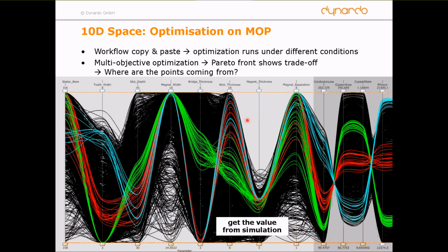The other extreme case is you go through one simulation, you change something, you look at the field lines, you look at the torque, you look at the details, you look at the mesh, you look at everything you can visualize in the simulation, and you can find out, wow, the torque ripples are really coming from here. Look at the field lines here, how they are distributed. I can explain exactly where the torque ripples come from, and then somebody asks, okay, so what can you do against it? Oh, well, that's a good question. Well, we could change something here. We could also change something here that has this drawback, that has this drawback. Yeah, so what are we doing?